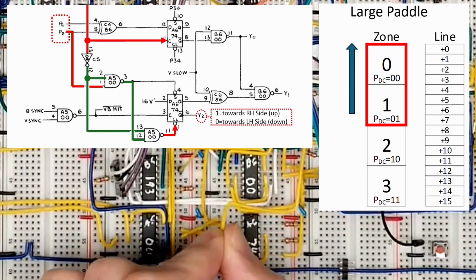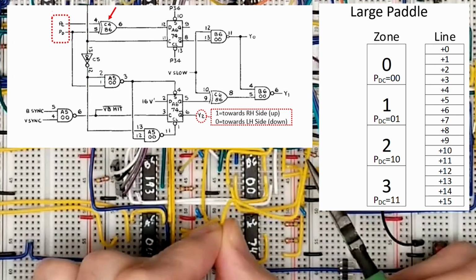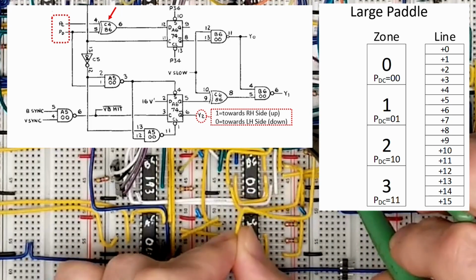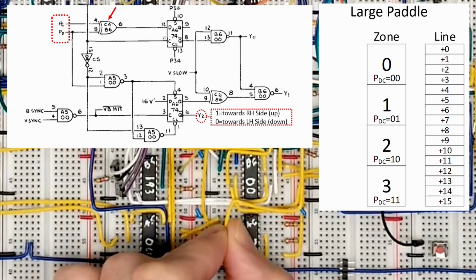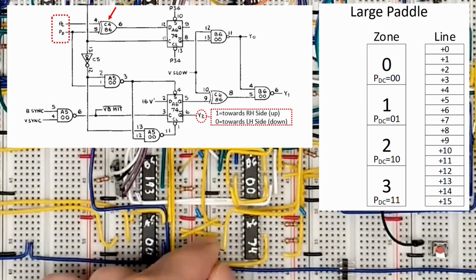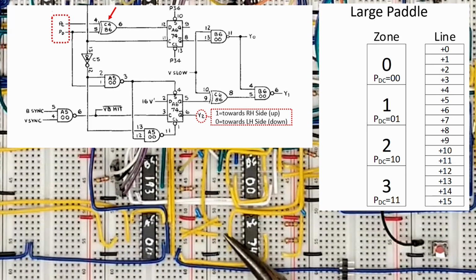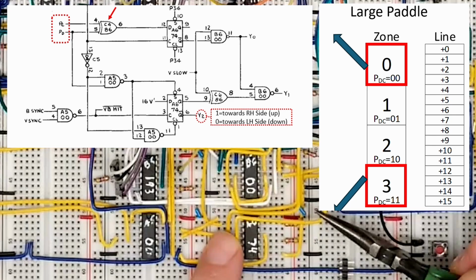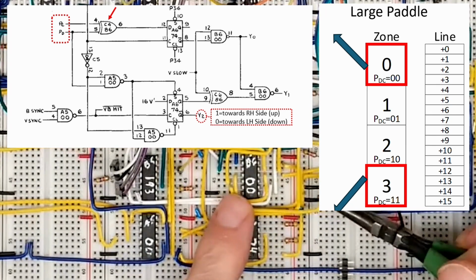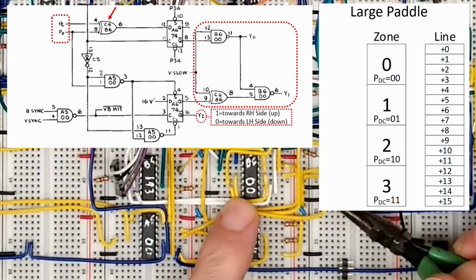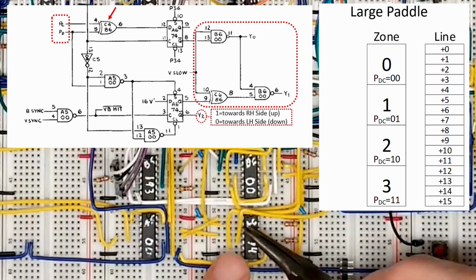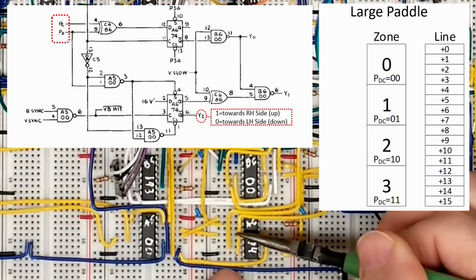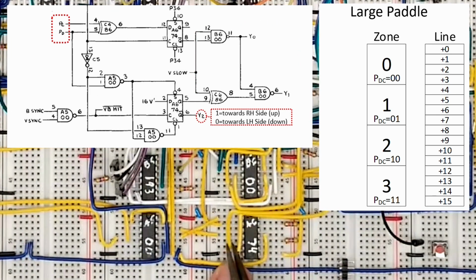For the upper latch, the output of this exclusive OR gate is on when only one of PC or PD is on. So this latch is set when the ball hits the center and is reset when the ball hits either outer edge. The rest of this logic adjusts the speed. You'll notice that there are no resets in this section, so the Y motion latches will retain some state.